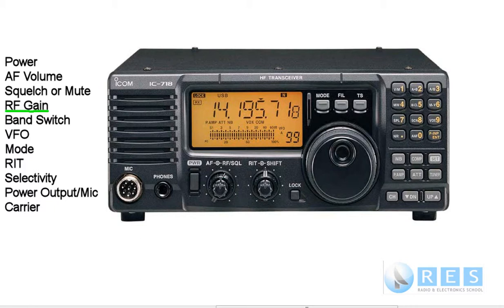And the RF gain is this control here on this radio. So you would rotate the RF gain in a clockwise direction to increase the receiver sensitivity. If your mute was open, if your squelch was open and you rotated your RF gain up, you would hear the noise increase.